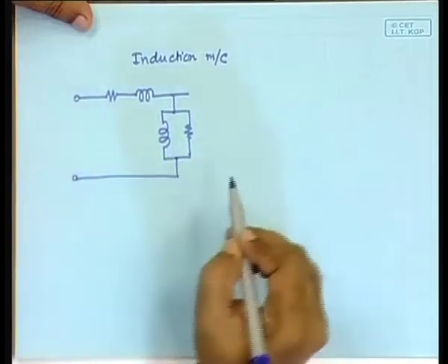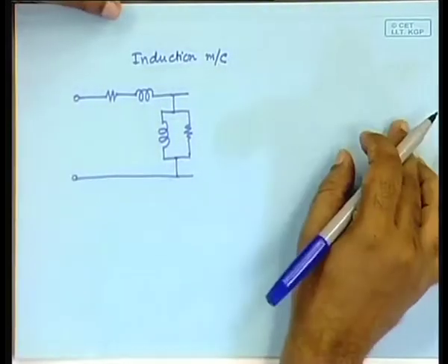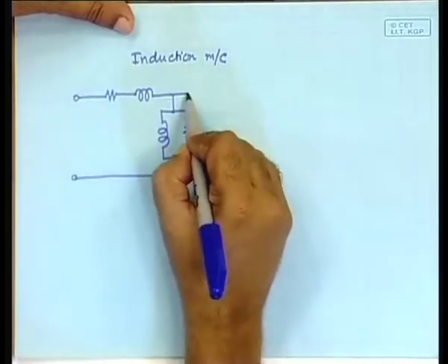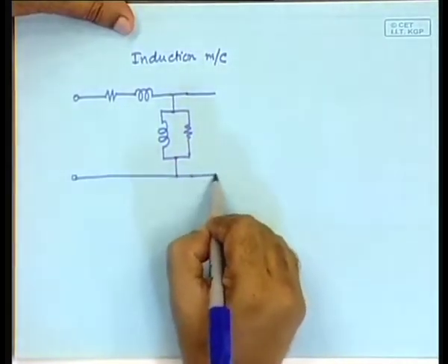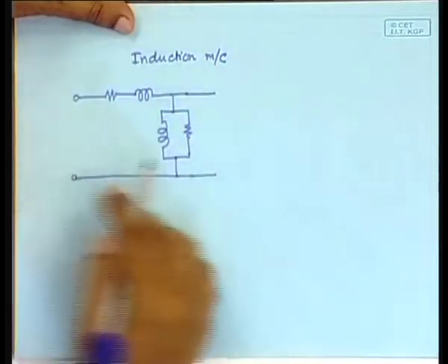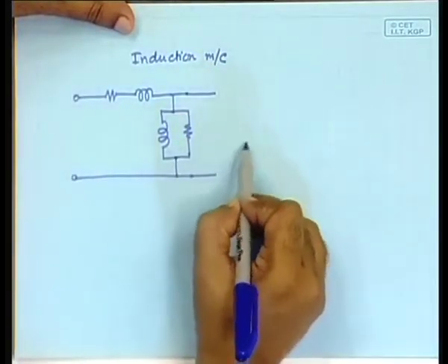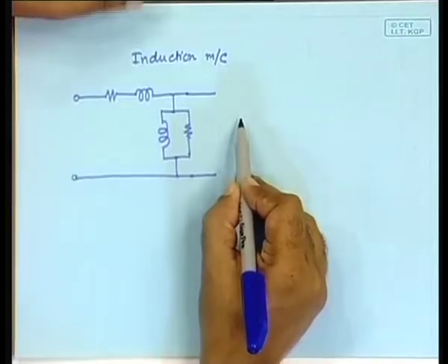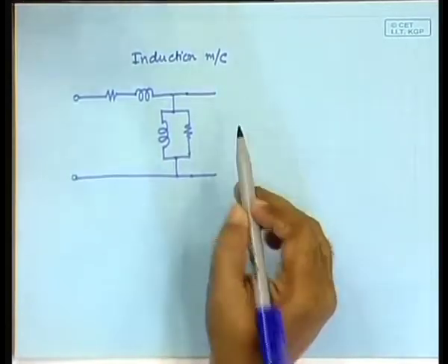These represent the eddy current loss and the hysteresis loss. And then we said first that here, after this has happened, there should logically be a transformer, and that transformer here will firstly represent the turns ratio between the stator side and the rotor side, and secondly turns ratio will make the voltage different. But not only that, there will be a difference in the frequency in the rotor side also, because the rotor bars, when it is rotating, see a different speed of rotation of the stator field.